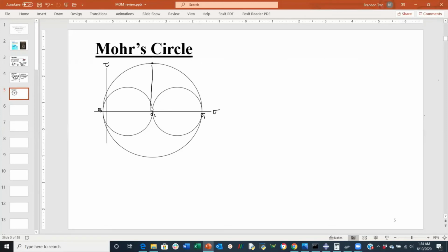And generally, which is correspondent to the center, generally the maximum shear, so it will be tau max. The maximum shear would be equivalent to your largest principal stress, which we identify as sigma 1, minus smallest principal stress, sigma 3. So essentially that's the radius of this circle here. And that essentially establishes the entire stress system. The maximum normal stress is obviously only in the principal stress directions, and the maximum shear stress occurring here. And notice this right angle right here is phi of 90 degrees. Phi of 90 degrees is the equivalent of 45 degrees